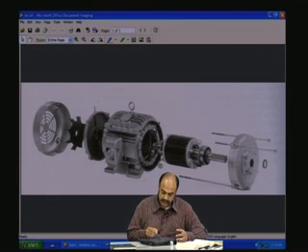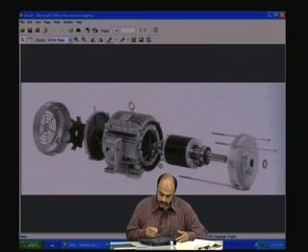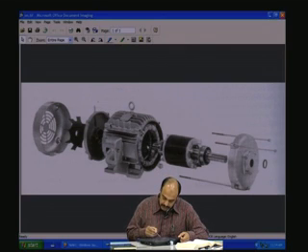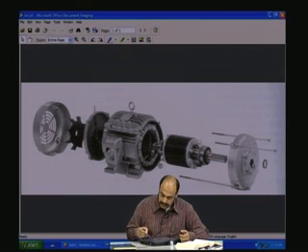That is why we say that the poles are fixed in space, they don't rotate. What makes the flux rotate is the three-phase source that you supply, which are 120 degrees apart. And this rotor is inserted into it, and then you have the end facing plates. This is one end plate and this is the other end plate, fitted through these bolts, and then there is the bearing, which fits in here and causes a smooth rotation of the shaft.